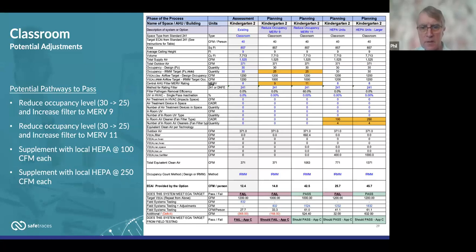Yeah, in this case, the testing in that one is shown to be a little better because of the effect of the MERV 11. You actually get a benefit, because on the MERV 8 you don't really get a filtration benefit in the HVAC calculation. So when you add up the values in there, you're getting a benefit from the supply air that you don't really see on the MERV 8 filters.